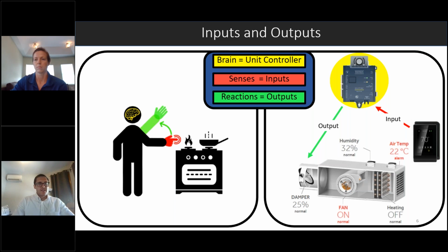Compare that to a VAV box controller, pretty similar. So we have a space temperature sensor, and that's sending an input to your controller, determining whether or not you're at the space set point that you want to be at. So if you say you wanted that set point to be at 68, and currently the room's reading 70, that controller would then go through logic to know, all right, I should open up my VAV box damper a little bit, get some more cool air into this space, and try to cool back down to our 68-degree set point.